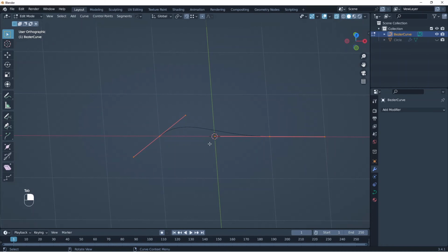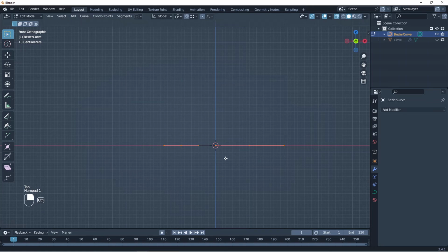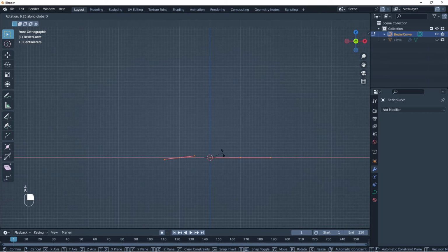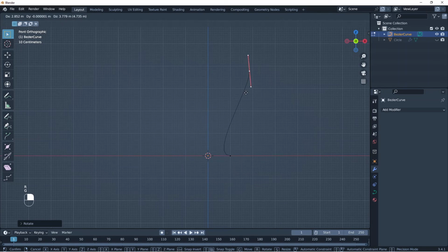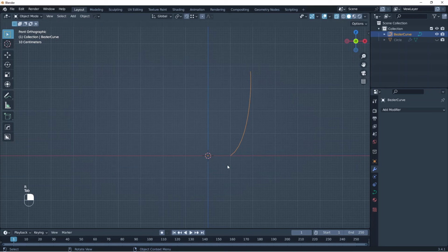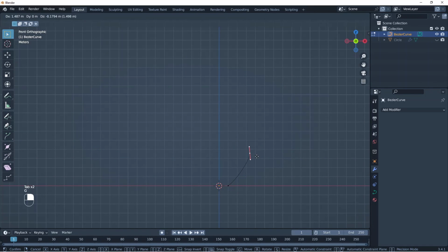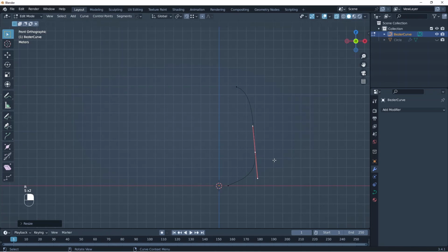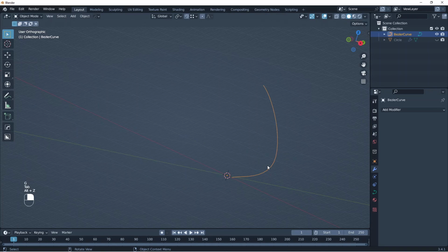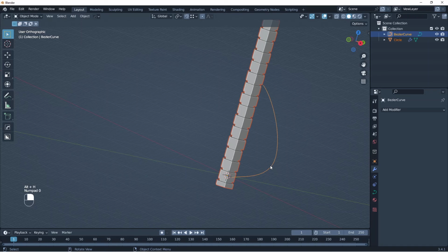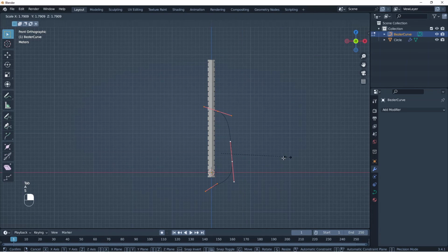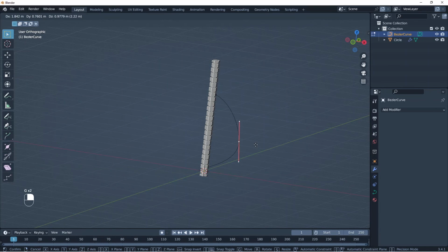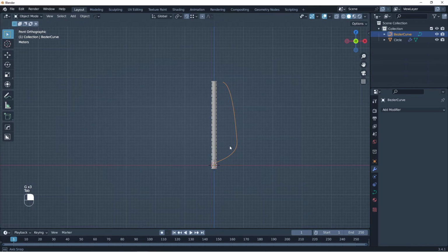And we want to go to edit mode whenever we want to make any change. So I'm going to rotate it on the X 90. See, I'm doing it in edit mode, so the location and the rotation remain the same as the beginning. That's very important, and I'm going to show you why. This is what creates a lot of problems if you don't do it this way from the beginning. So I'm creating this curve, making it bigger, and doing that. Yeah, that's fine.